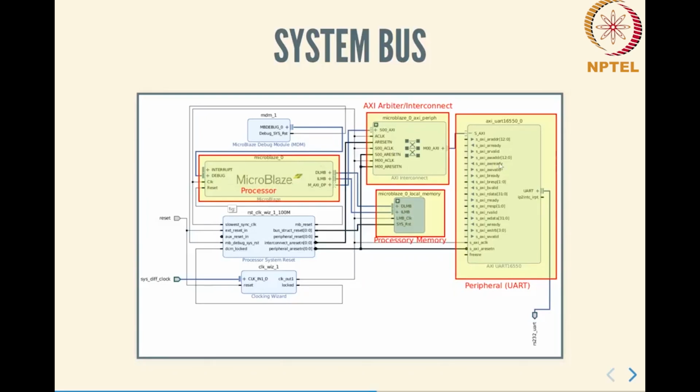In our case, we have only a single peripheral, the UART, and the UART interface of the AXI bus has been expanded. So you can actually see that it has a large number of related wires over there. Going from the top, it essentially has something called AR address, which is basically some kind of a read address. There's an AR ready, which indicates whether the address is ready, AR valid, which is an input from the CPU indicating that the address is correct. Similarly, write addresses, write ready, write valid, a whole bunch of signals that you don't need to worry about for